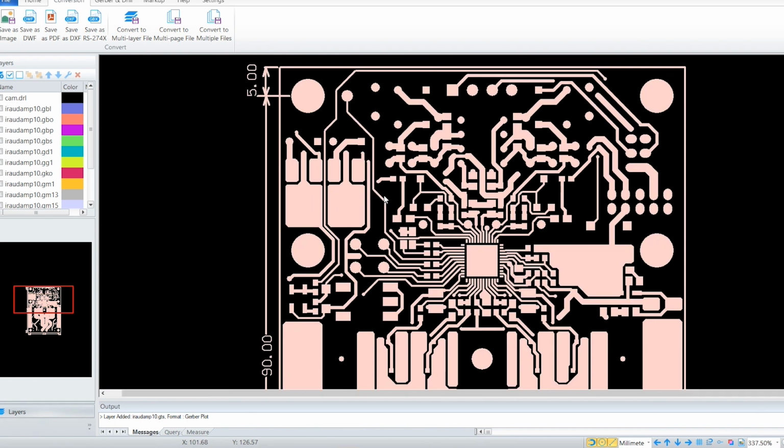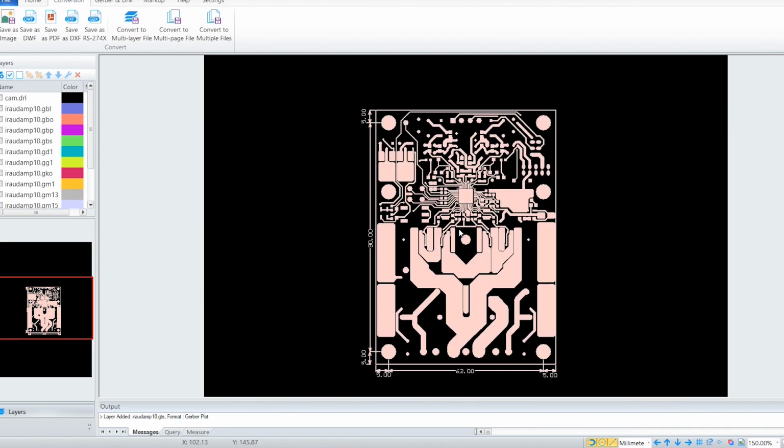Could you live with high resolution pictures? Generally yes, but if you're really going for 10 mils or even less than 10 mils, where 1 mil is 1,000th of an inch, or 0.025 millimeters, it's not sufficient. You will have additional challenges already in the exposure process. This is why you need perfection in a film.